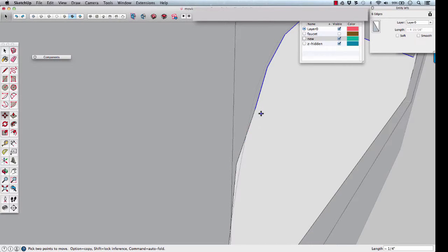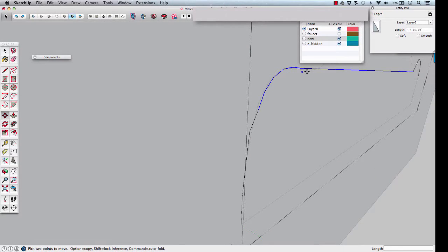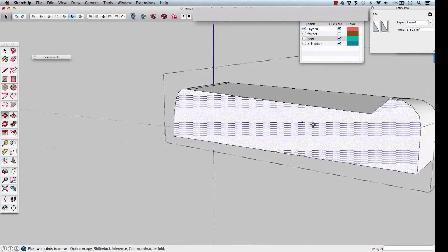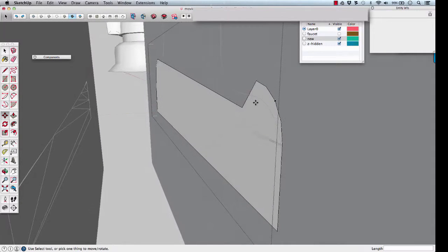This little line segment here got bent and it could move down, but we also want to move the profile back out a little. I'm going to select this edge as my edge to lock to, hold shift, come out here and click and move it out till it matches the profile underneath. Now clear the selection, click on just that end point, and we'll move that down a bit, maybe to there. So we've just adjusted that profile to match that next downstream profile.